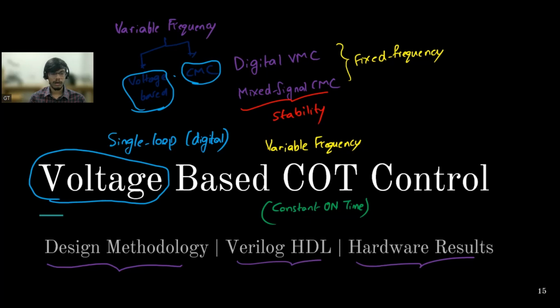At 2 ampere, we can have the corresponding current reference for 2 ampere. Similarly for 10 ampere. But we are using both the inductor current as well as the capacitor voltage in our control, so it has two loops. So we have much more degree of freedom because we are using both current as well as voltage in designing the control.